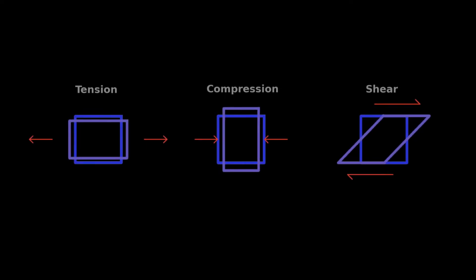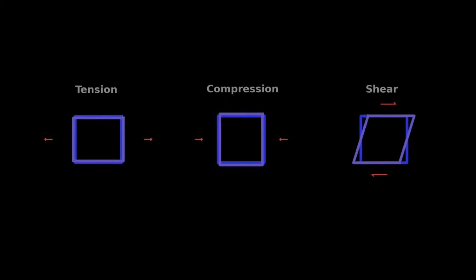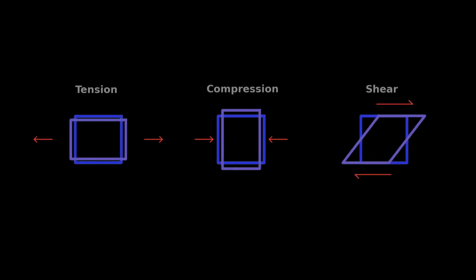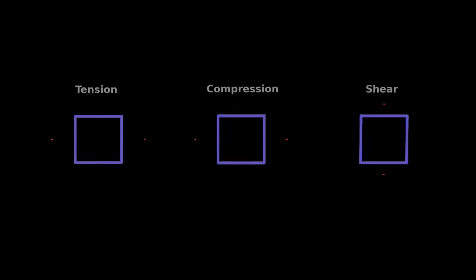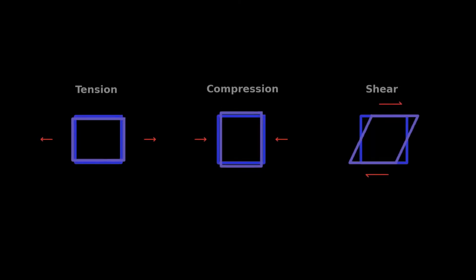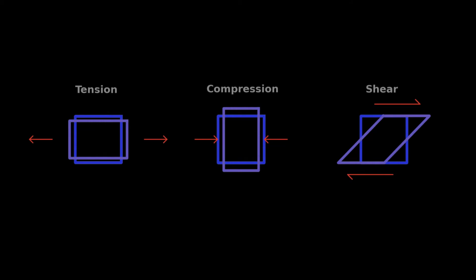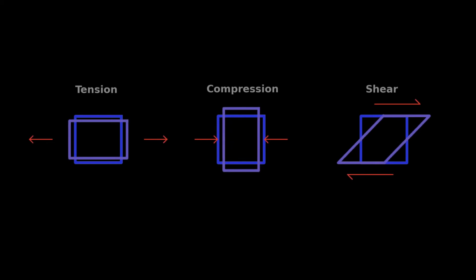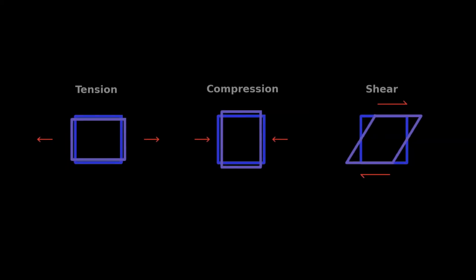Some materials have a tendency to fail when subjected to normal forces, tension or compression, while others fail in shear, like scissors cutting by shearing material. Generally speaking, brittle materials have a tendency to break in tension, while ductile materials have a tendency to break in shear. So, to get the most out of the materials we have, we use them in applications where they are strongest.